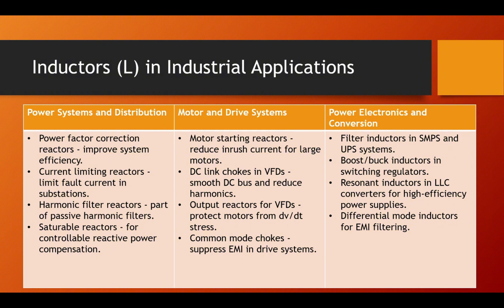Lastly, inductors are also used for power electronics and conversion. We use boost or buck inductors in switching regulators and resonant inductors in LLC converters for high efficiency power supplies.